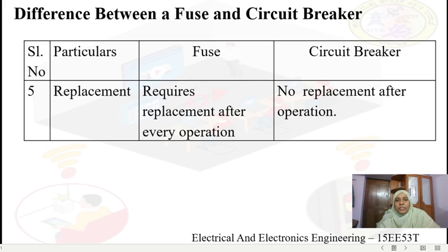So these silver vapors and the filling powder which is around this element will have a chemical reaction and a substance is produced which has high resistance, right? That is the reason why your arc which would have appeared during the fault will be quenched, and then your heat will also be reduced. So your filling powder does two works. One is quenching of the arc, the other one is cooling the medium. So this is how your fuse works. Right? So next we saw the advantages, we saw the disadvantages, we saw your applications and differences between the fuses and circuit breaker. I hope today's session is clear.